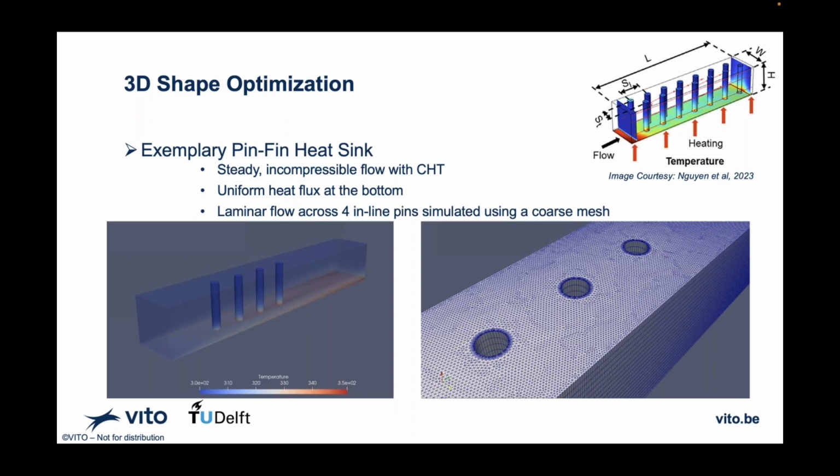And as you rightly said, currently I'm using only the deformation settings, the elasticity model available in SU2. As we have large deformations, the topology is still maintained, but that leads to poor mesh quality. So indeed, one of my next steps is how to have regeneration smartly integrated.